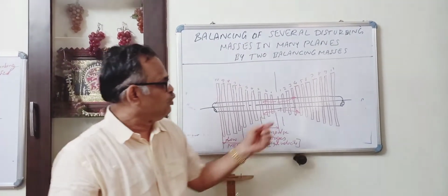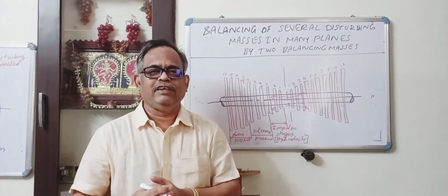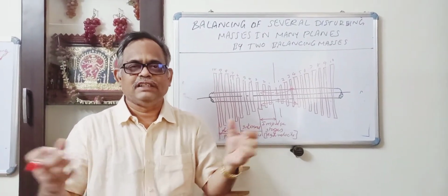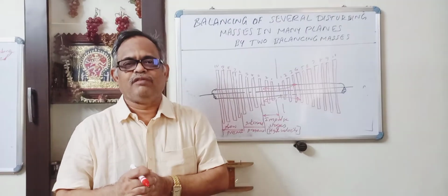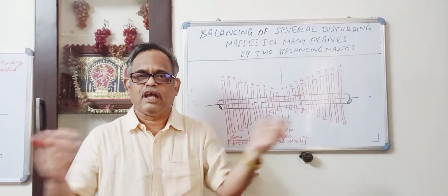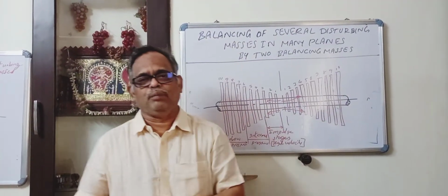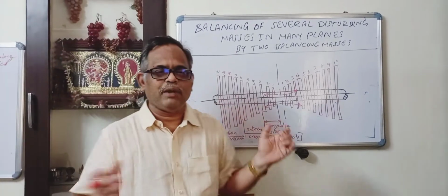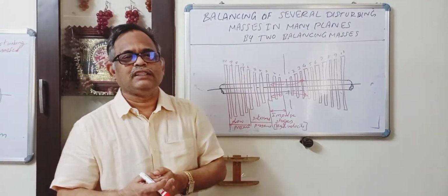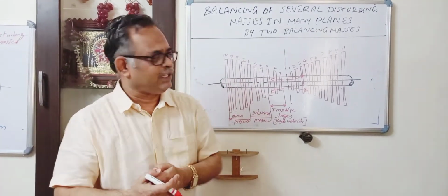Now they have made the design in such a way that the generator and the steam turbine have the same RPM of 3000, in order to avoid the gearbox. So nowadays steam turbines are designed for 3000 RPM, whereas small turbines are designed for 6000 RPM. So industrial turbines are designed for 6000 RPM, right?